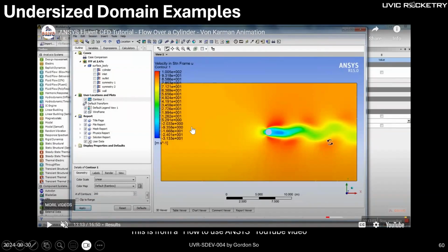However, if you look closely, you can see upstream slightly change too. So again, this is something that's visual, and I'm sure there's a way to quantify if this is big enough. But my guess would be you would look at your boundary condition and your flow to see if it's capturing everything. And if you look really close, you can see this downstream condition also affects here. So you can see the domain is not big enough because it should be bigger to avoid this happening.